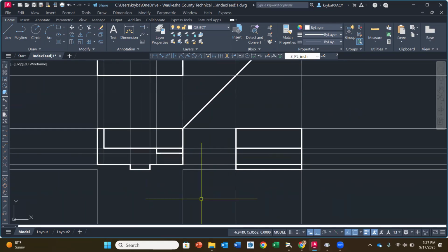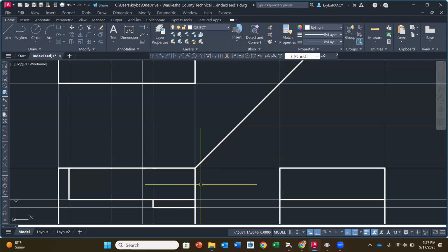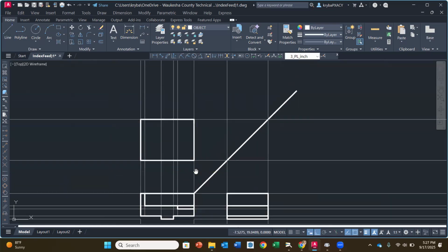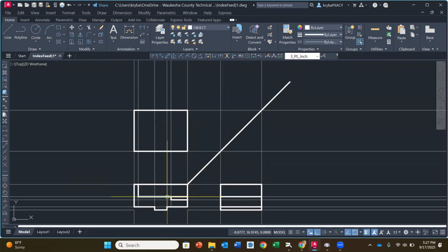Okay. So got to kind of stop there for the right side view. So that means we're going to have to go up to our top view. Okay. And that's good. All right. So a couple things. If we know that this part at the bottom is going all the way through, okay, we can put the hidden lines in there right away because it's on the bottom of the part and we wouldn't see it in the top view. So I'm going to change to my hidden line layer. And I'm simply going to draw from intersection to intersection each one of those lines on either side in projection again with what's down below. Okay. So that's just representing these two lines right here.